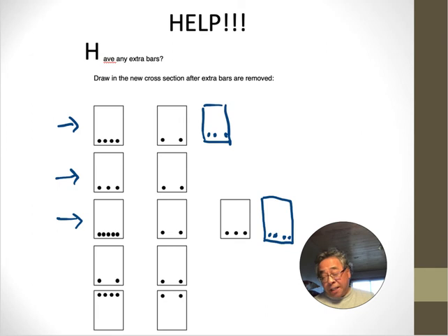And in all cases, we've not taken out more than 3/4 of a bar. Remember, you have to have 1/4 of the bars going all the way across. 2 bars, there's nothing to cut, right? 2 bars just stays at 2 bars. And this is the one you really want to do. If you have 4 bars on the top for negative moment, you do want to try and get rid of 2 of the bars, so then it's easier to place the concrete from the top. And you need to keep 2 bars at all times because they help in the cage construction for the stirrup.